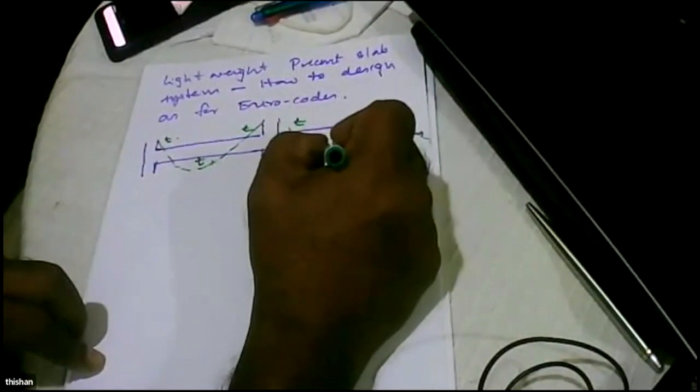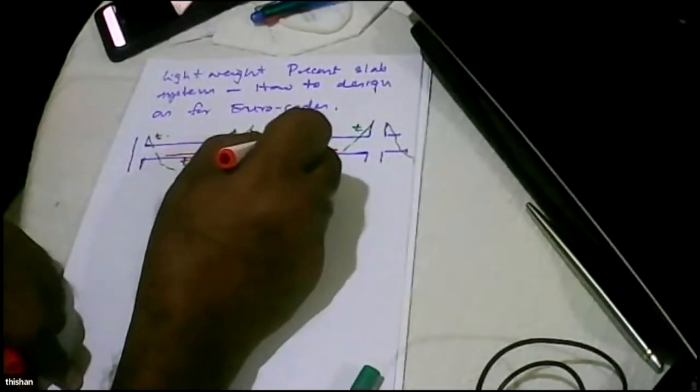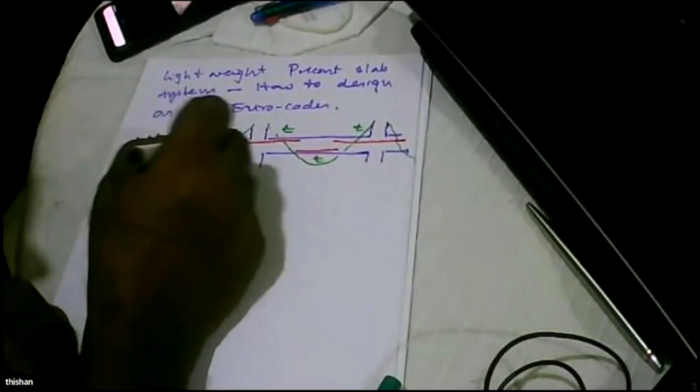Right. Now to resist this tension, we provide reinforcement here. The moment we provide the reinforcement, what is the next thing that happens? This side goes into compression. Here again you get compression, and here again compression.